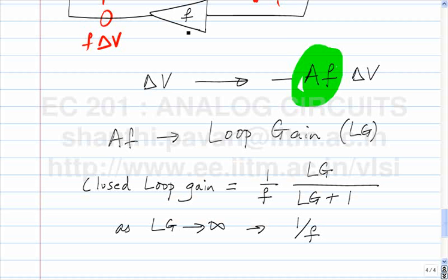One is to design the forward amplifier with as large a gain as possible, and the variations in the gain don't bother you anymore, because the properties of the closed loop system are very, very insensitive to the properties of the forward amplifier, as long as the gain of the forward amplifier is sufficiently large. And the second part of the problem is to make an attenuator whose properties remain sufficiently stable with process and temperature, and that is quite straightforward, as we have discussed.